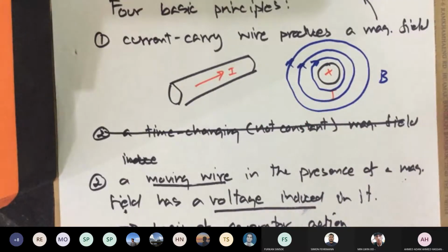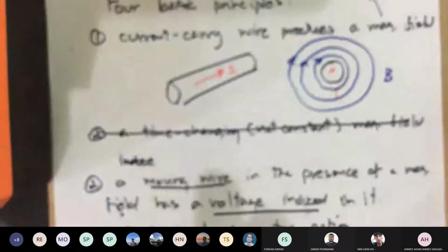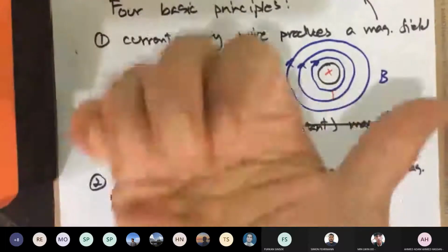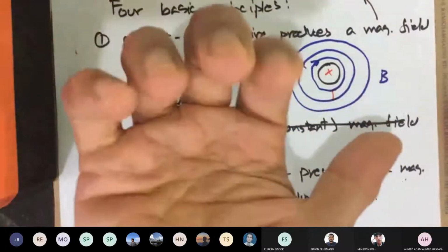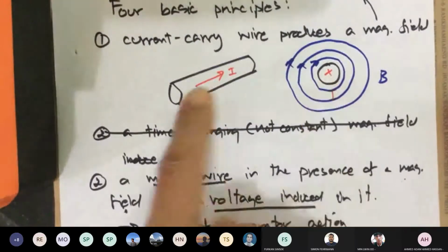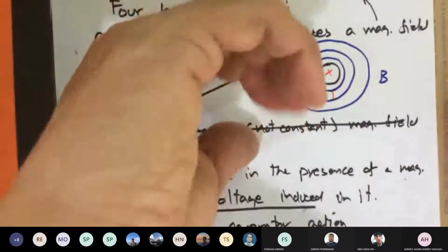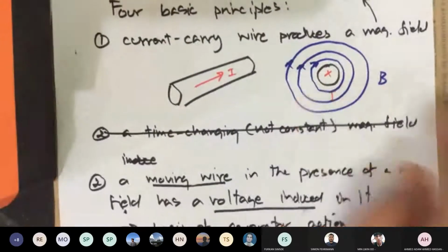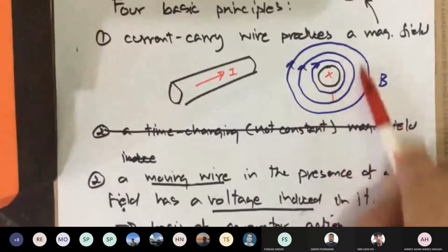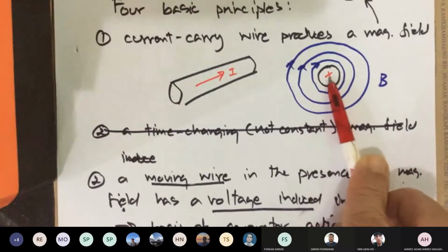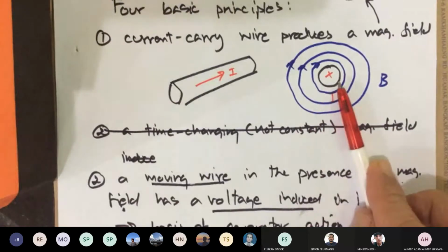How do you do that? You use, I think in English, it's called the gripping right hand rule, okay? So here my thumb points to the direction of the current. In this case, kind of like outward. All your fingers are the magnetic flux. So in this case, this is the cross section of the wire. So your current would go into the page. So your magnetic flux would flow counterclockwise, shown here. And the flux would produce the magnetic field around the wire. Okay, so the wire is that black. I'm not sure you can see between blue and black. So this is rule number 1.